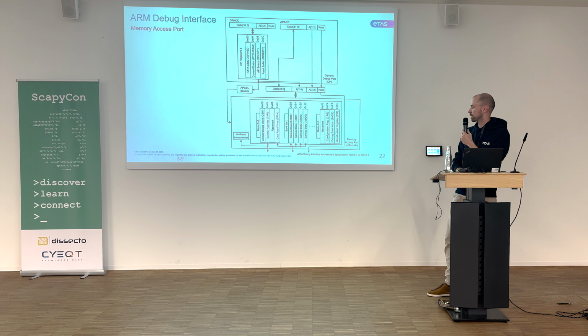Here we always have these identification registers. For any access port, you'll have a value here, and that's how it knows what this is, and then it tells you a lot of information about it. So if you just want to do basic introspection, you can just define some stuff in OpenOCD and then ask it about the different access ports.